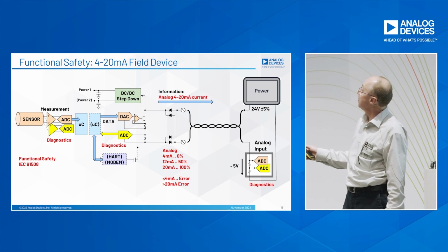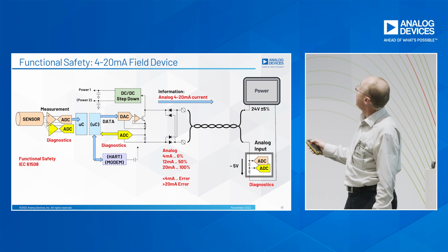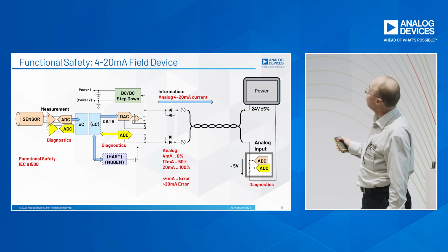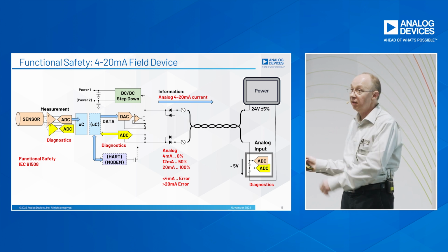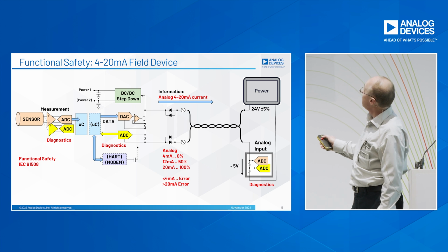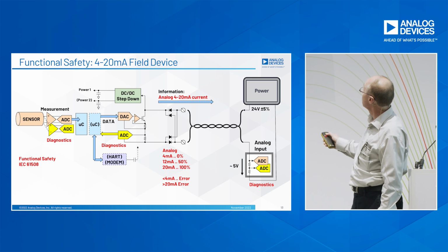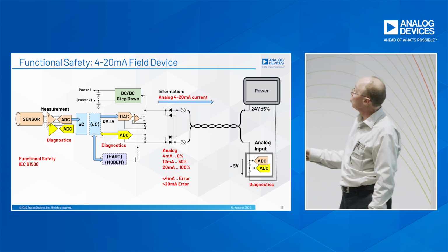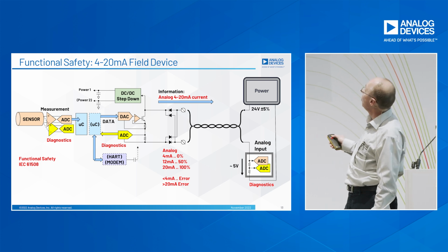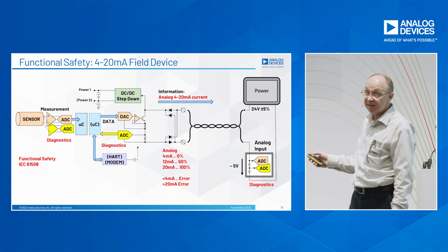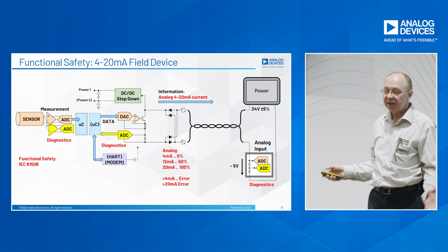So you would see typically another resistor and ADC looped back to the microcontroller, and similarly on the input side, on the analog input side on the controller, you would see redundancies there. You wouldn't rely on one resistor. You would have two resistors, two A to D converters, again to make sure that what the sensor measures, that information gets all the way down there. And if there is any fault detected at any stage, you have to declare that the sensor can't measure.